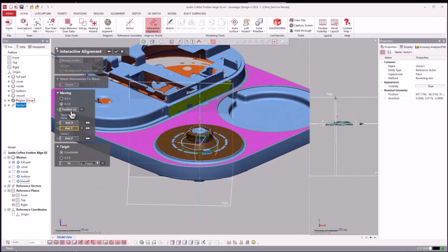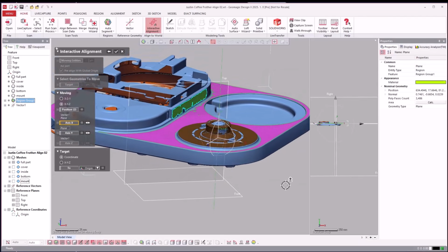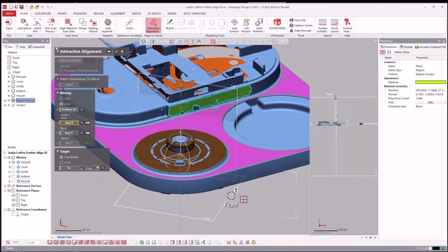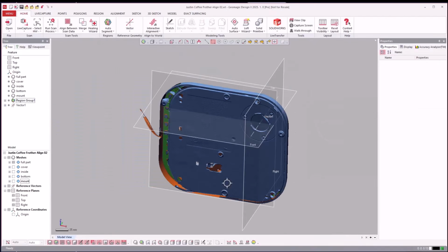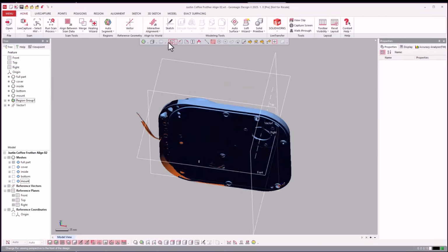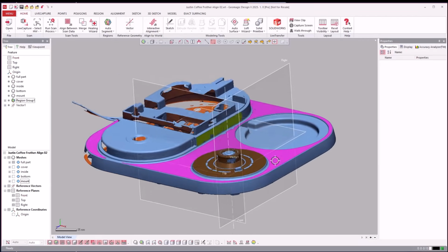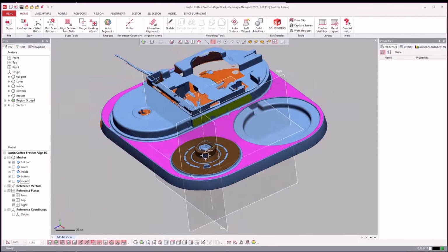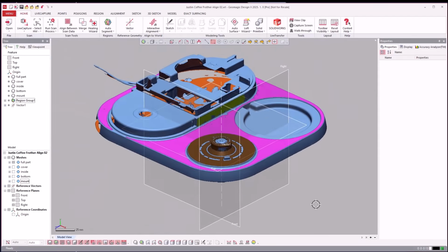And then I will say the x-axis, I want it to, do I want x or z? Say x-axis there. So you see now I have fully constrained it, hit OK, and go align, boom. We have my coordinate system. All 3 planes are at the center of this.